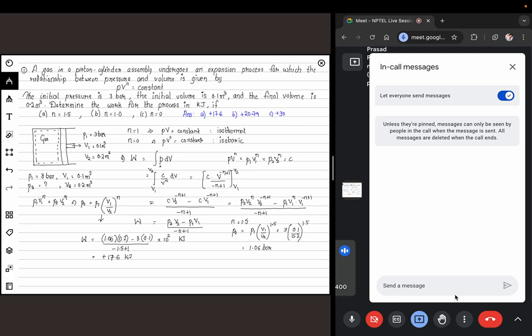Again, coming to the notation, if work is done by the system, we consider that as positive, and work done on the system is considered as negative. Here, as the gas is expanding, it is pushing the piston outwards, so the gas is doing work on the piston. My system is considered as a gas. Now if I would have considered the piston as my system, then what would be happening to the piston?